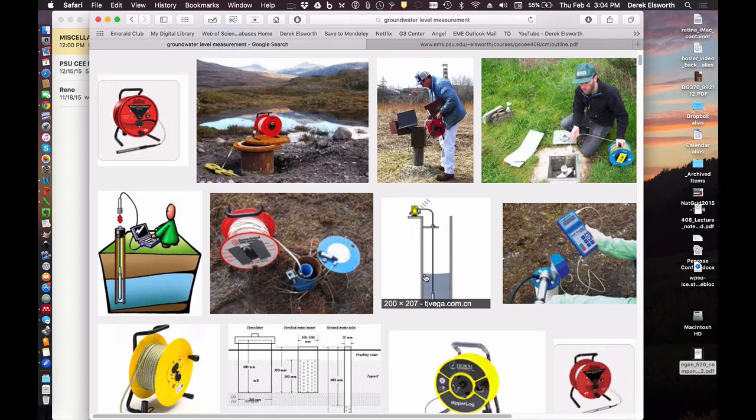Those may be either buoyant things in there that measure water level rises and telemeter back, or it could equally well be a pressure transducer sitting at some depth. Water goes into the casing, it fills it up higher, you measure the pressure, and immediately you get a water level that you can telemeter back to USGS for them to upload onto their website, which they can also correlate with a flood stage with a flow rate.